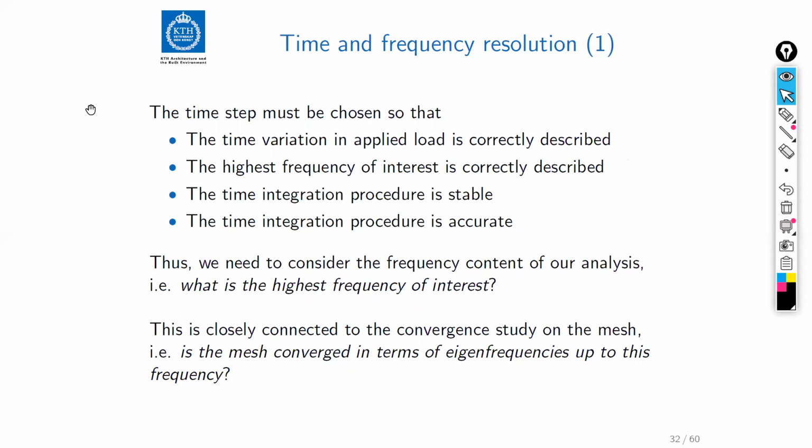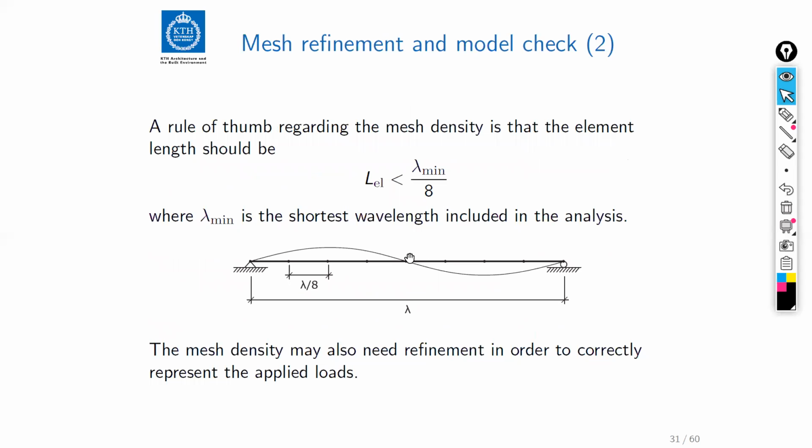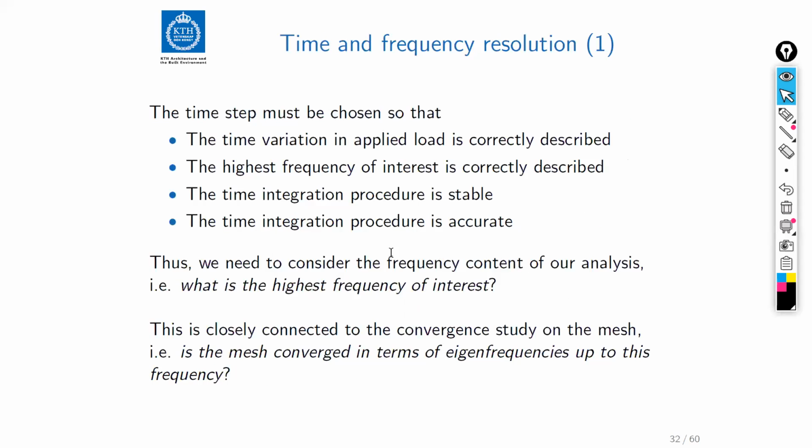But once you get over that threshold, you can again set up some rules of thumb that make life really easy. And I think here, in choosing the time step, we need to consider the time variation in the applied loads, of course, just as we need to discretize space here to be able to represent the wavelengths that we are looking for. We also need to discretize time in a way that can describe the variation in the loads.